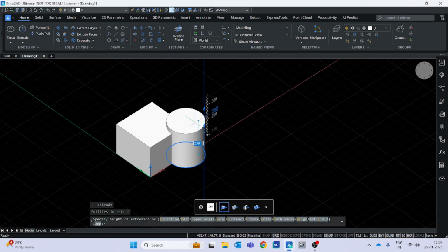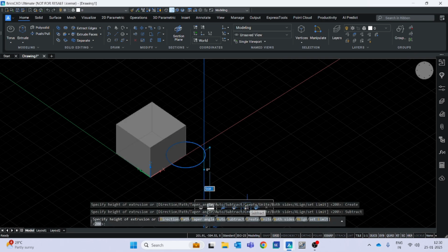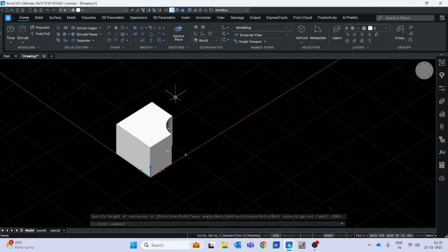If you hover around, we can see this hotkey assistance which shows the boolean operation that can be done, whether you have to make an extrude, make a cut, or join it. It always shows the option at the bottom. I'll control click on this twice and make sure that I need a cut on that. So this way you can create the simple extrude and extrude cut.